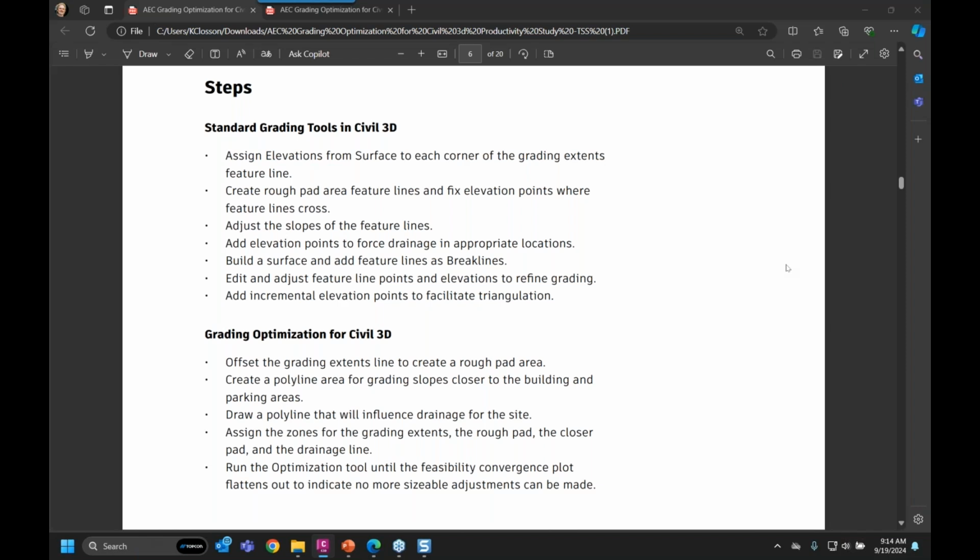Okay, this polyline is going to be a building pad, and this is going to be the parking lot over here, and this is going to be a sidewalk, curbs and so forth. And when you're doing that, we can go in and say, are these break lines? Or do they have a little bit of play in them? Is it a constraint or an objective? That's a key terminology that we'll look at here along the way.